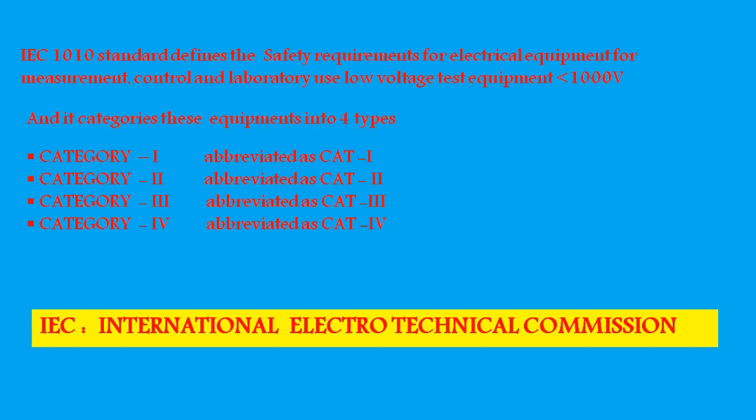First, category 1, which is abbreviated as CAT 1, and category 2, which is abbreviated as CAT 2, and in the same way CAT 3 and CAT 4. They divided these categories based on the possibility of transient voltages that may occur in the measurement equipment while at work. Higher the possibility of a transient voltage, higher is the CAT number.